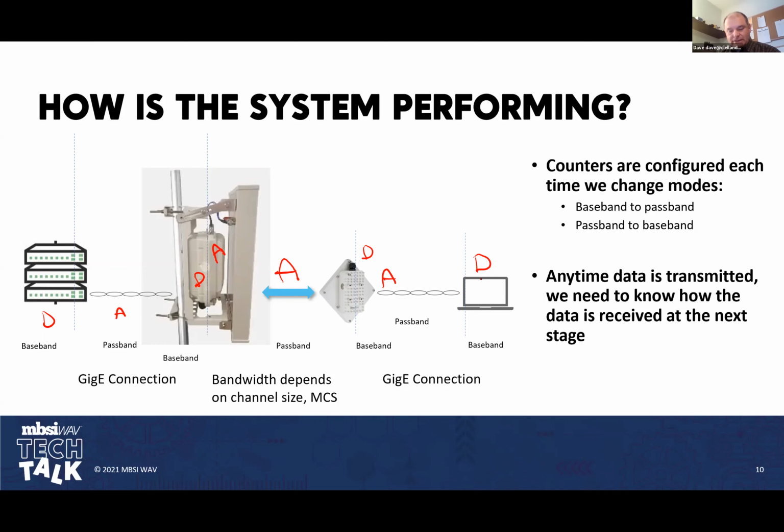So this is the way to look at it: we're baseband, then we go to passband over the connection medium, then we convert back to baseband inside the radio. We process all the data, and then we convert it back to analog over the air, so it's passband at that point. Then we hit the CPE, we become baseband, and come out of the CPE with Cat5 or with fiber optics, whatever it happens to be.